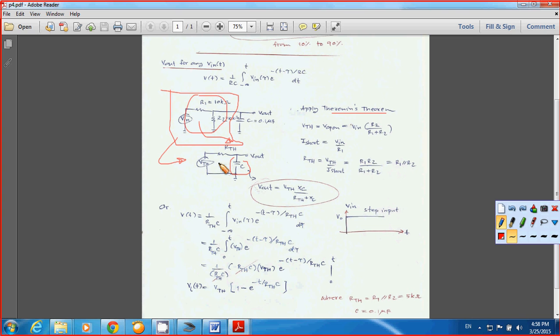Easy to calculate, and it's back to the previous circuit, just like we talked about. RTH simply becomes R1 in parallel with R2. So that's why I have RTH here as R1 in parallel with R2. I'll actually repeat how to apply the Thevenin theorem to the circuit again. You still remember your RTH simply becomes R1 in parallel with R2, and this is your load.